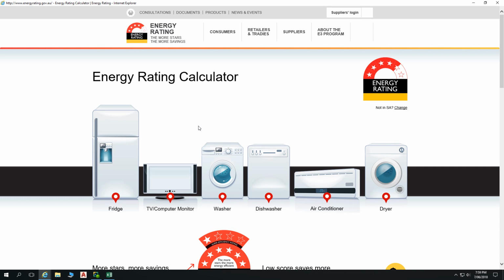Sorry, Mike, I just overheard you talking about the lights. Yeah. It says here a warm white downlight, LED, 825 lumens. Yeah. So 125,000 divided by 825 gives you the number of light fittings you need for the floor.